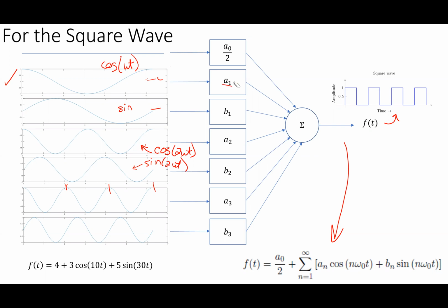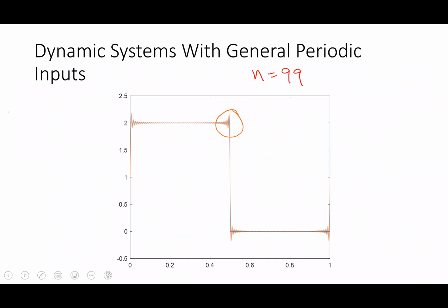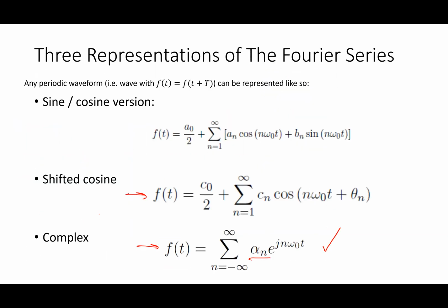Based on what I worked out, and we'll figure this out later, at each of the harmonics, at B1, if you go through the math, it's 4 over pi. At the third harmonic, it's 4 over 3 pi. And if you keep going for the general nth harmonic, it's 4 over n pi. So basically what that says is,